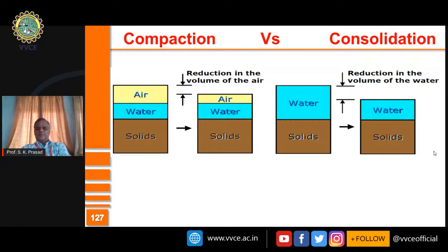On the other hand, consolidation, the spring mass analogy is very ideal to explain consolidation settlement. This is also volume reduction, but because of the expulsion of water. So this can be seen only in saturated soils, saturated clay soils, and it takes a longer time for water to expel out. So we should have a good knowledge of the two phenomena, compaction and consolidation. What we are talking about is consolidation, and it happens in clay soil, in fully saturated soil.